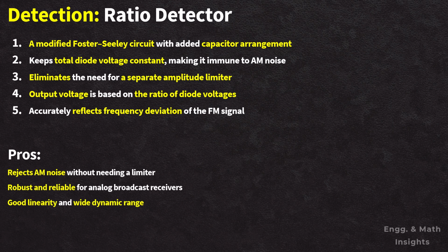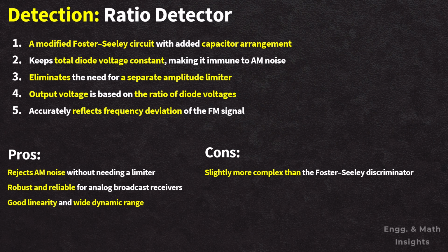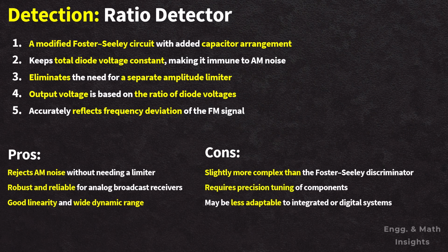good linearity and wide dynamic range. Some cons are this is slightly more complex than Foster-Seeley discriminator, requires precision tuning of components, may be less adaptable to integrated or digital systems.